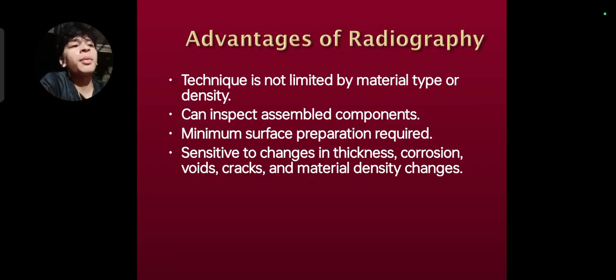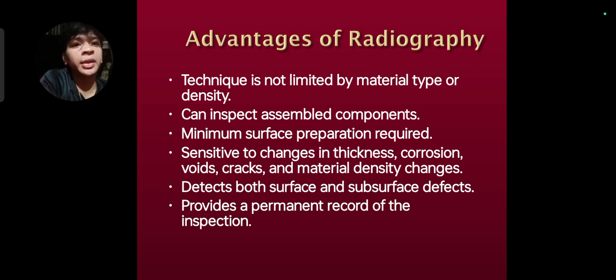Now let's talk about the advantages of radiography. The technique is not limited by material type or density. This kind of testing is not limited to what material it is, unlike PT or penetrant testing, which only requires smooth and non-porous materials. In radiography, all types of materials are applicable.